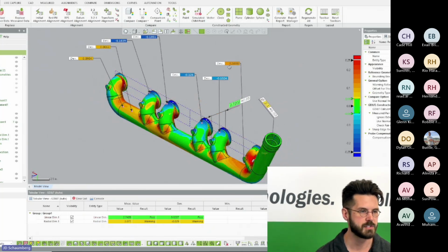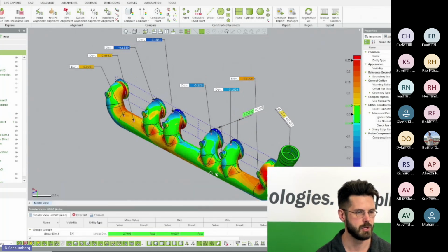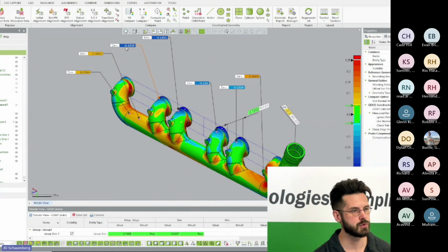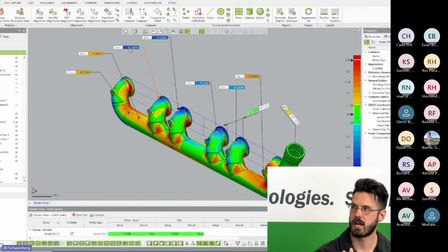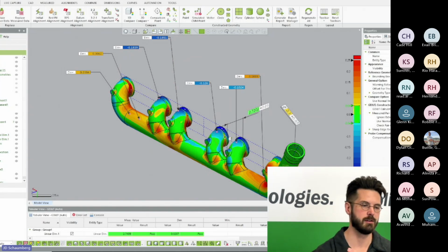So I've set up a single view the way that I want to see it on the screen here. Let me adjust this down a little bit. Also, another quick note about the color maps inside of Control X. The Control X product is actually the inverse of the Design X product. So the accuracy analyzer inside of Design X is looking at CAD versus scan. Here we're looking at scan versus CAD. So inside of Design X, these blue patches were red, but they're blue here because we're analyzing in the reverse direction. It's the inverse.